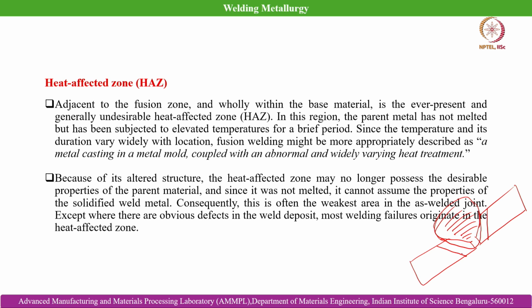The heat affected zone is the region of the joint which is exposed to a high degree of temperature generated in the region of the weld pool. However, it does not experience complete melting, but it experiences thermal softening. If it is a precipitation hardened alloy, then the precipitates can get coarsened or it can show an over-aged structure.